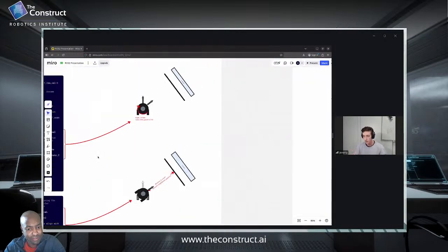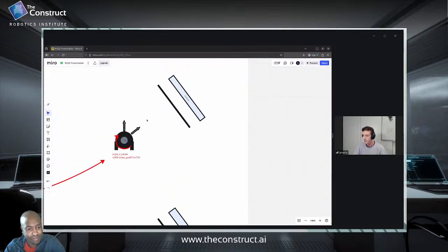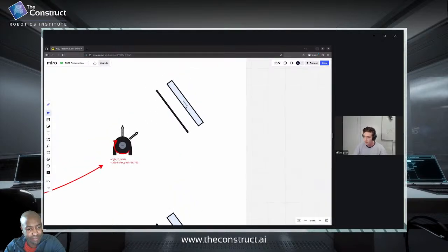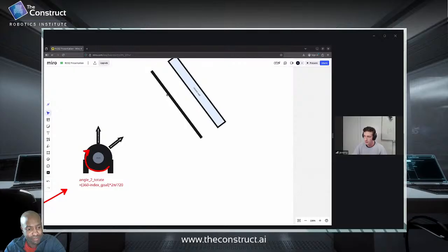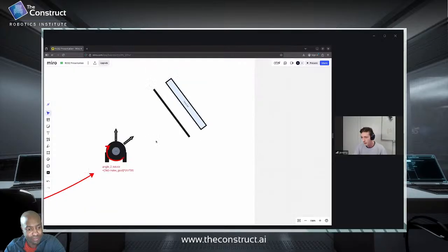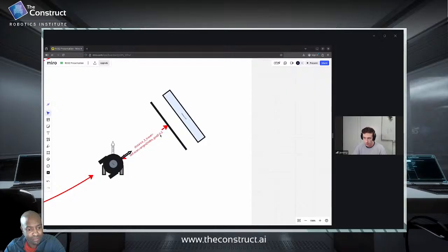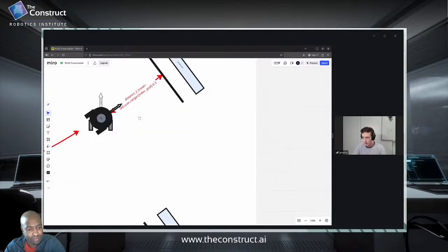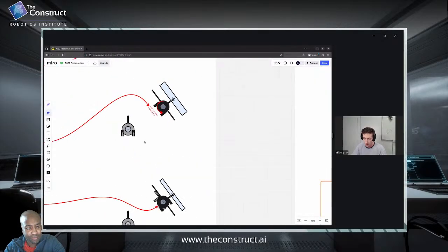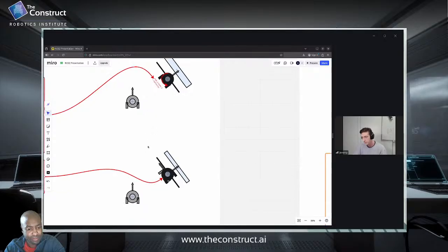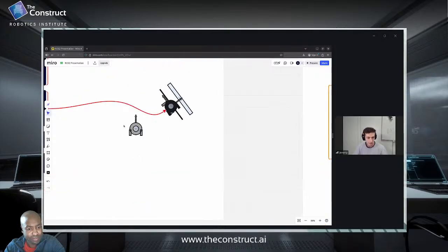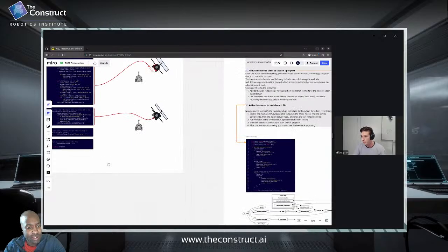I would send a message to the steer publisher and adapt the velocity. So here it's just a schematic. I would look for the shortest ray. This is the wall. This is the buffer distance of 30 centimeters, and I would say, well, spin in the right direction, move forward, considering that little buffer of 30 centimeters. Go there, and then once again just spin 90 degrees to keep the wall perfectly on your right, and then start the topic that we've just done before. Okay. So just coding logic.